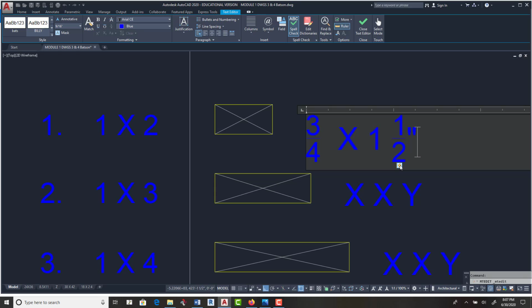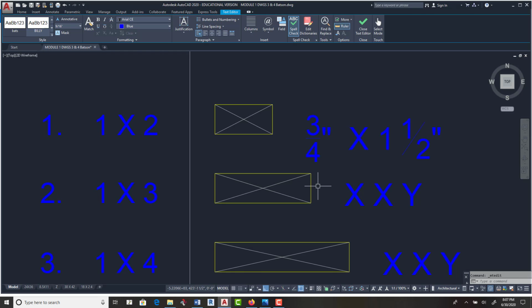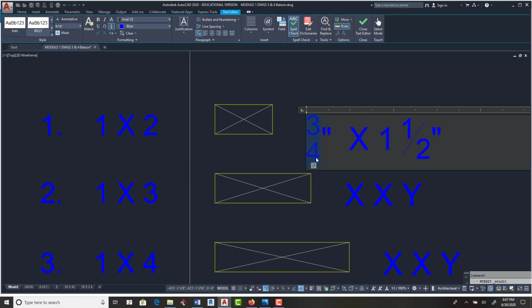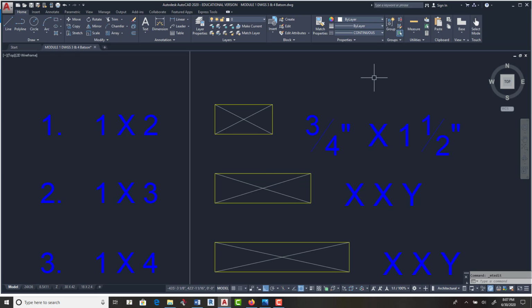Okay, when you put the inch mark on it, it clicks on there and you can say diagonal. And this is supposed to be 3/4 inch, okay? And you can make this a diagonal fraction. There you go. So once you get that, let's see, this is moved down. I would move it back up. I would sort of make sure it's lined up right over here, right there.